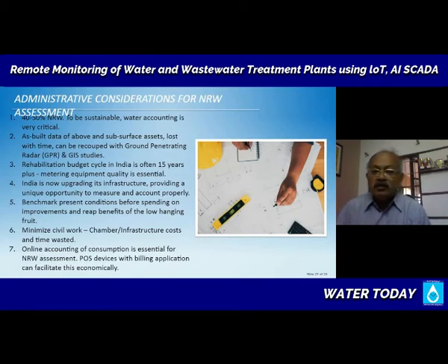So these are all very cost-effective ways of obtaining asset data that is below ground. And of course, if you have assets that are above ground, a GIS study, you can do drone-based mapping nowadays, which helps you to record your infrastructure very, very accurately. So these are very cost-effective ways of digitizing and establishing your asset infrastructure where it is. All these pipes that have gone in over the years, different pipe materials that are there below the ground. You can have all the interconnections and the valve chambers and everything identified and all the records available so that you go from people dependency to system dependency. So this is something that I would like to recommend very heavily for the water industry. Please record and know where the assets are so that you can manage them.